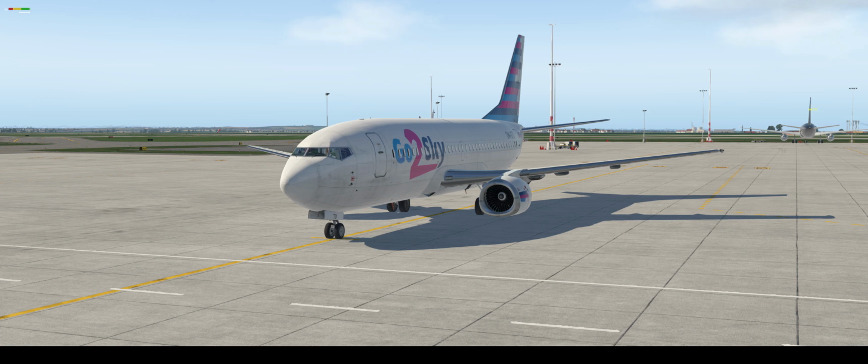Okay, and what are these rules about? It was 1 hour of flight training. Okay, it was just the ground training, but anyway, first of all, you must remember that this airplane is the longest, and I'm not talking about the NG 900. This airplane is the most critical to tail strike.